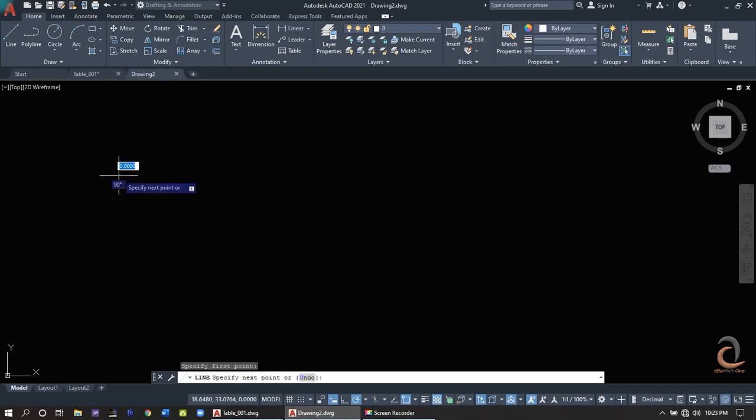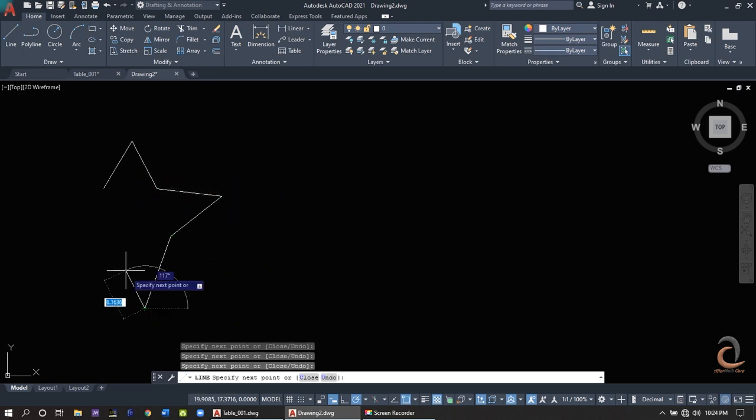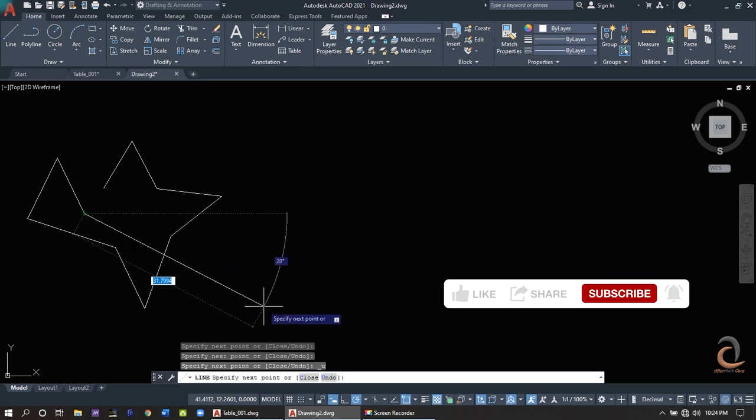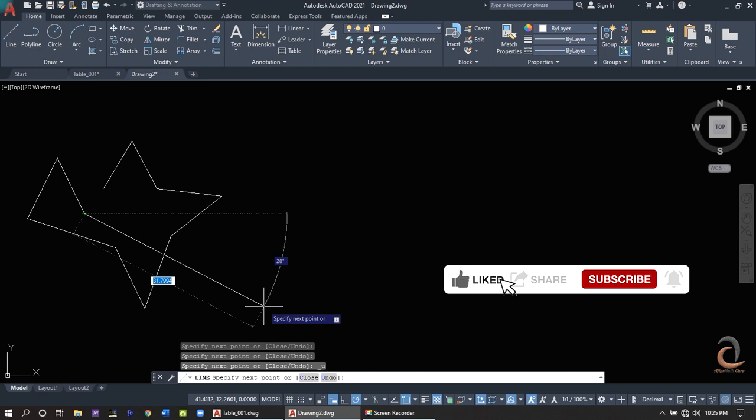Left-click to pick a point on your model space. Join me in picking extra points. Now, you can see that the command line words has changed. AutoCAD is not just asking for another point, but there are now sub-options in a square bracket. Sub-options are more options which are available inside an active command.